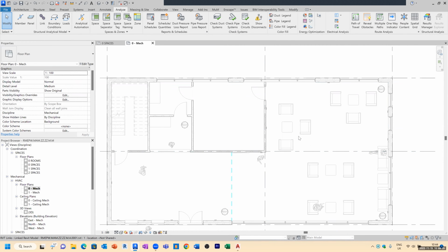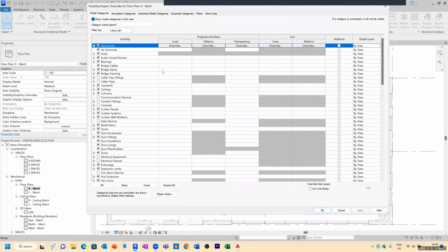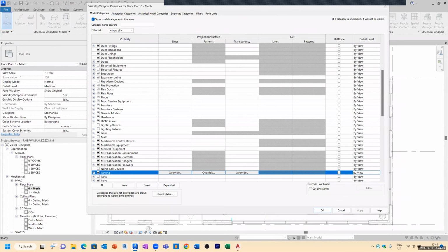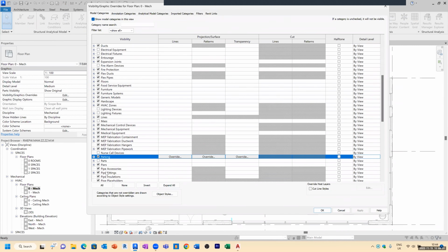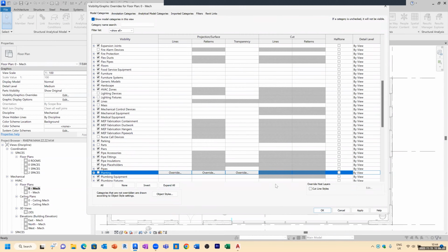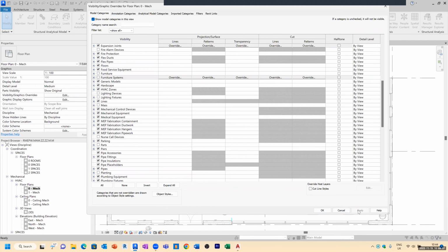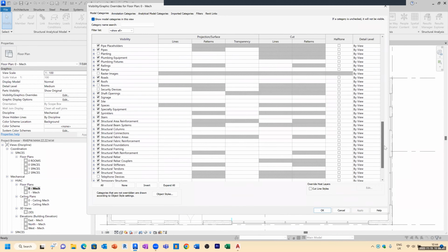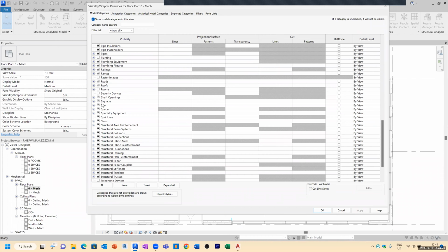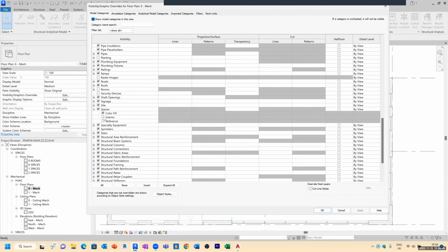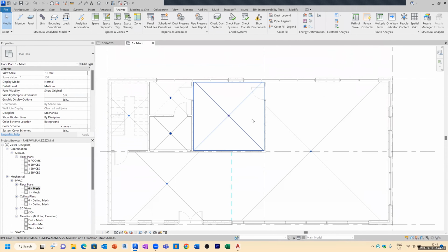And again, we've got various things on here we don't really want to see in our design. So let's turn off the planting, I think it was. And the furniture, we don't want any furniture on here. And hit apply. We kind of want some space names maybe on here. So let's go down to spaces. I think it's the reference. Right, okay. And you can see those spaces have been defined there.